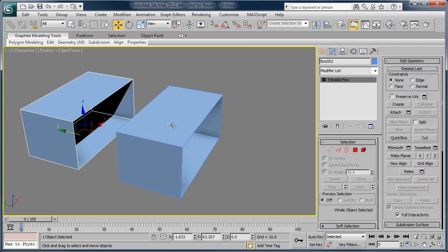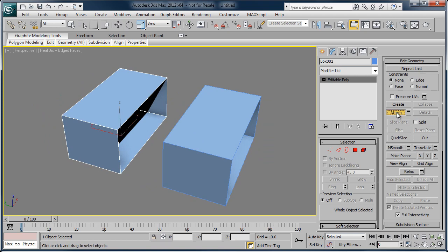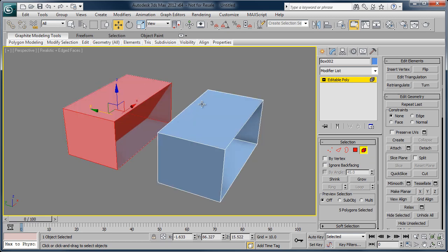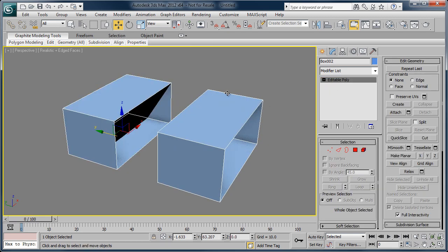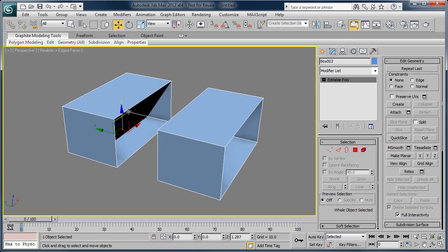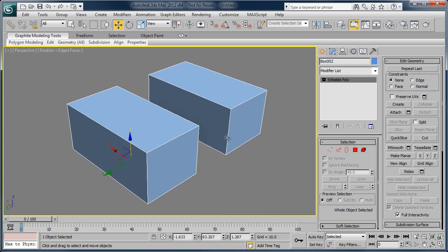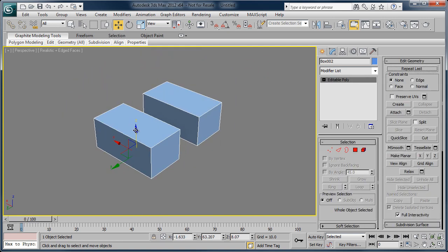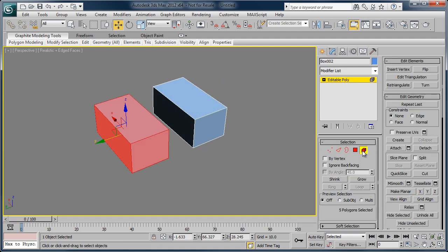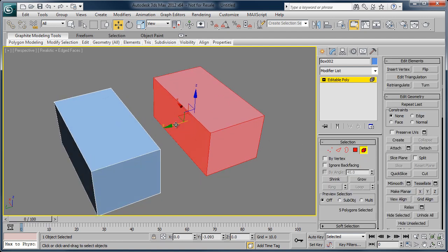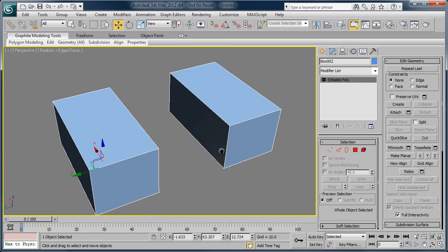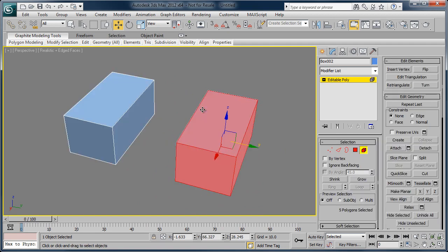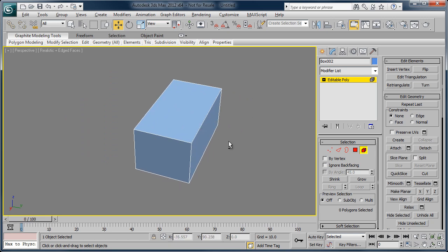Now the element mode, this is traditionally utilized when you have, let's say, 2 objects and we make a copy of it over here, and I'm just going to run through this quickly, and we'll cover the specifics of these tools in just a minute. But element mode is basically when you have 2 individual pieces of what is considered one single object after you have attached them together. This is a tool that we'll be utilizing a little bit later, but it just means that once you have 2 objects that have become one, you can quickly go back into the element mode and select that individual piece of that specific object. And if you also wanted to get rid of an element, you can grab the entire element itself and just press the delete key.